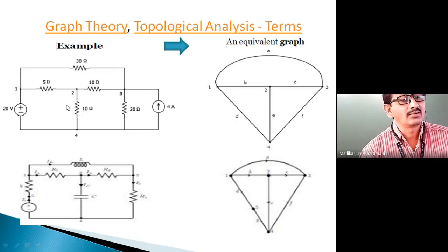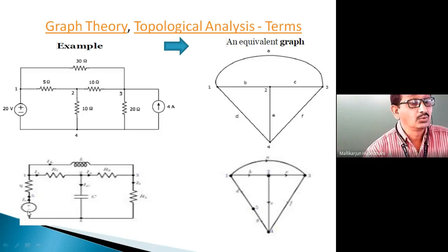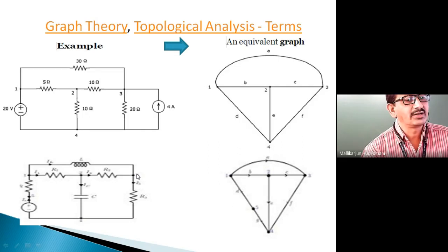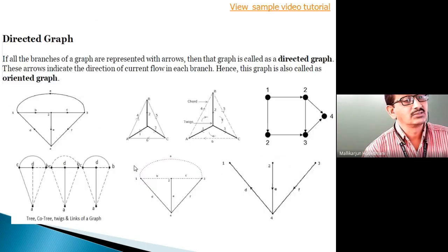This is how an electrical network is represented by graphical connectivity. Similarly, I have another diagram with a voltage source, capacitor, and inductor shown. Wherever there is a physical contact between any two buses by an element, that element shall be represented by a segment. Then my next work, once we are able to draw the interconnection graphically, is that orientation is necessary, which means we have to account for it next. Let's look at the next slide, how it works.